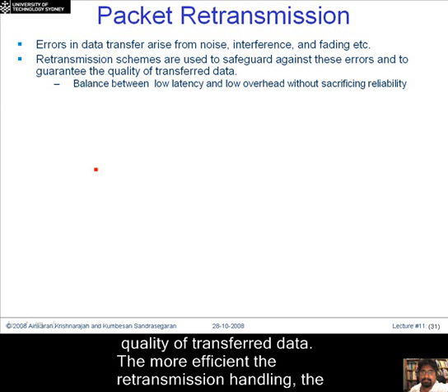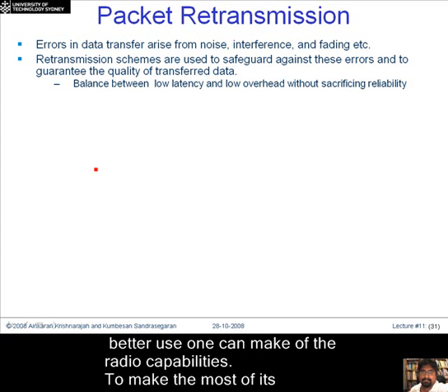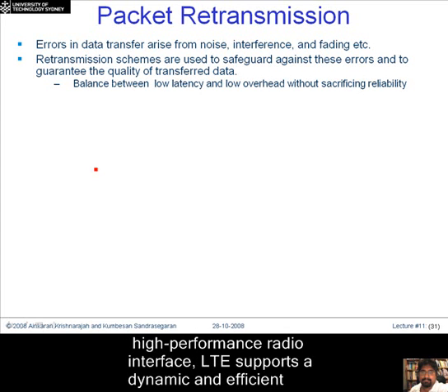Backward error correction schemes are schemes in which, when you detect errors in the received signal, you go back to the transmitter and say, look, can you transmit this frame again, because the frame you sent me was in error. So these schemes are also referred to as retransmission schemes. Retransmission schemes are essentially there to safeguard against the effect of errors.